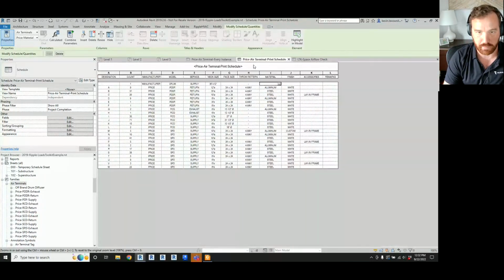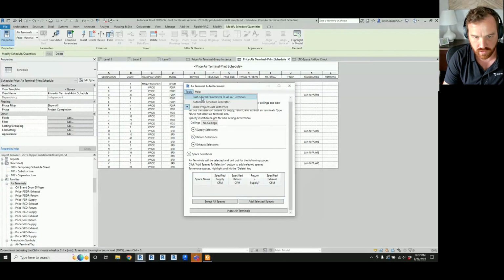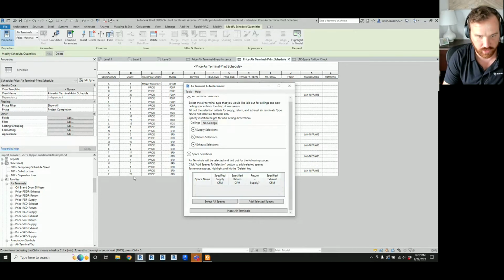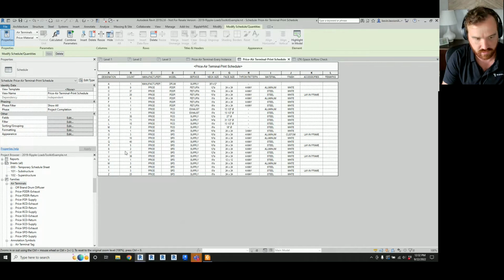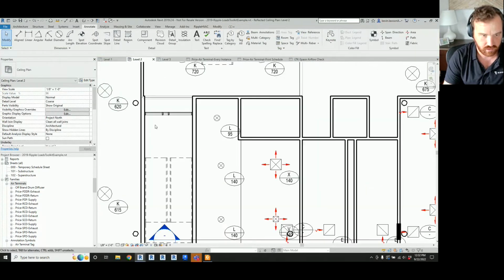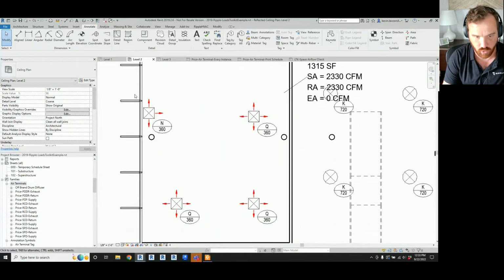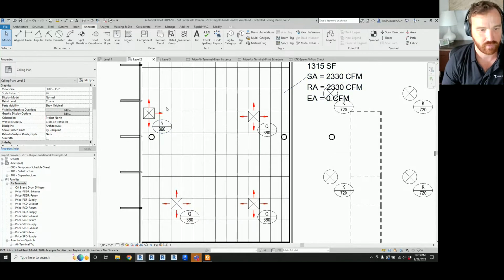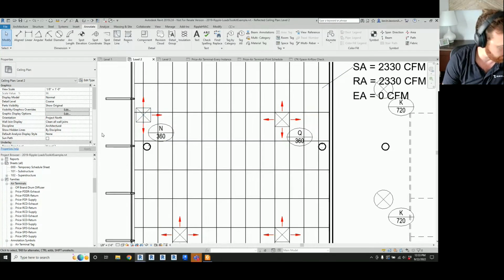It's in there somewhere. But you'll notice I changed a bunch of stuff, and now I don't have the correct designations on. So just make sure before you put this on the schedule, you rerun the schedule separator. So that's going to redesignate everything. Now I got my 12x12 here. I've got my 3-way here. So it separated my 10-inch 3-way from my 10-inch 4-way. And now that is forced to match the tag. Which all of this was just such a nightmare to coordinate before. So that's a really helpful feature.